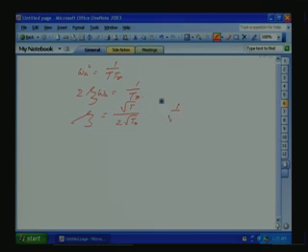That means 1 by root 2 is equal to root T divided by 2 into root Tr. This implies T is equal to 2 Tr. So, if you put T is equal to 2 Tr, you will get a good response according to the classical convention from our control system point of view with theta equal to 1 by root 2. So, we can use that one.